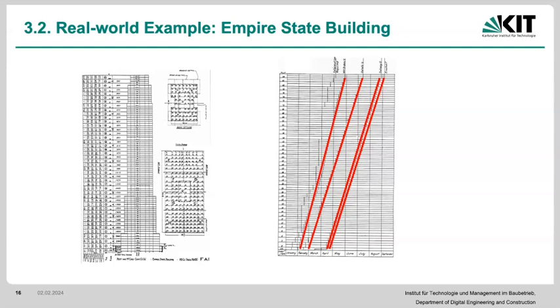Nowadays, we can actually even do the subdivisions in terms of every floor plan as well, and we can divide them as well. And that's going to be more or less what we call location-based planning. This is going to be basically linear planning that we're going to be talking about. And line of balance is a particular type of linear scheduling that I'm going to be talking about, which only attempts to optimize for flow of repetitive activities, okay?